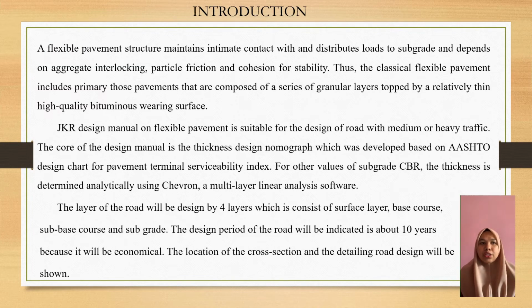For introduction, a flexible pavement structure maintains intimate contact with and distributes loads to the subgrade and depends on aggregate interlocking, particle friction, and cohesion for stability. Thus, the classical flexible pavement includes primarily those pavements that are composed of a series of granular layers topped by a relatively thin, high-quality bituminous wearing surface.